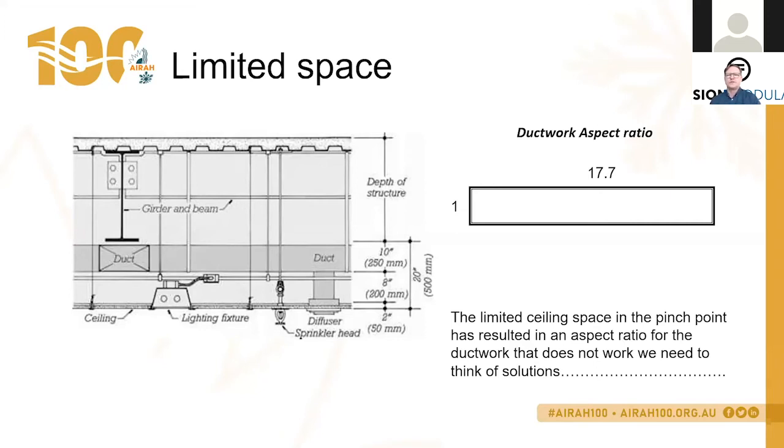So we should consider all these options in our ductwork design. And if necessary, we may have to do a performance-based solution on the insulation, and maybe make the insulation slightly thicker on the rest of the ductwork, where we have more space, and remove or have very thin insulation at the pinch point, so that when we have a larger amount of space at the 250 mil, we might be able to achieve 220 mil or more by using a different type of insulation material.